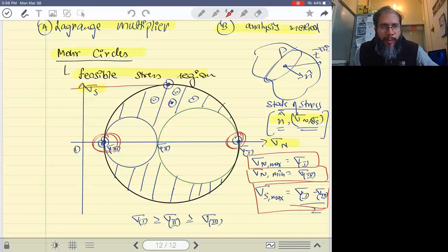Now, shear stress minimum, I mean, we can go in the negative direction, but that doesn't mean much. It's simply a change in the direction of shear stress with the same magnitude. So the minimum shear stress we have is 0. So usually what we do is we just draw half of this. We draw whatever's above the sigma s equal to 0 plane. So we are only interested in the maximum value of shear stress. The minimum value of shear stress is 0, which exists on the planes where you have only normal stress, or the principal planes.